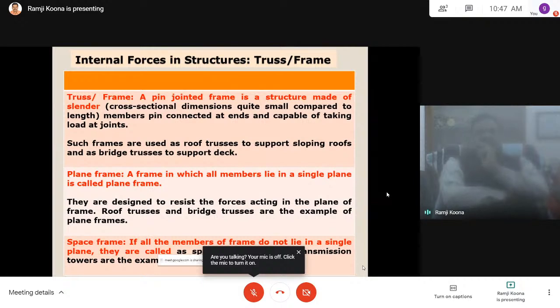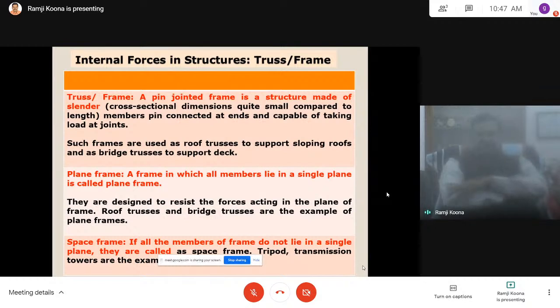So this is the difference between a bar and a truss. Both are one-dimensional, both are 1 degree of freedom systems. You can consider a 2-dimensional or a 3-dimensional bar also. That is resolving the forces, that's all. But the actual force is along the member, and that force you can resolve in any number of directions. See, that is the definition of a bar and truss.